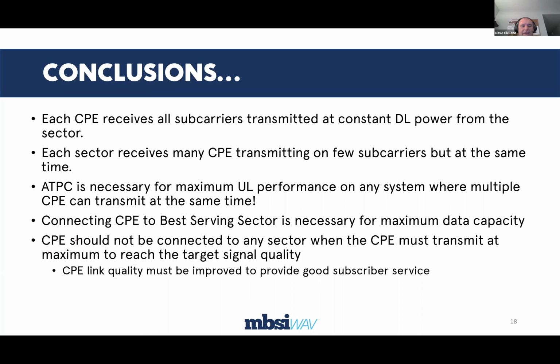So that leads to high performance, and it is good network design to have all of your equipment on the sector running at as low a power as you can to make your service work. So the business plan and the transmit power and your site selection and your CPE lockdown are all really important to the health of your network. So that's my little tech talk for today.